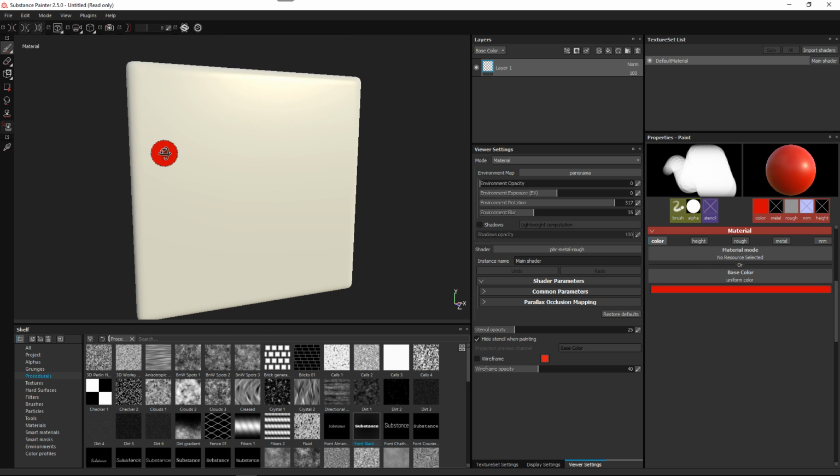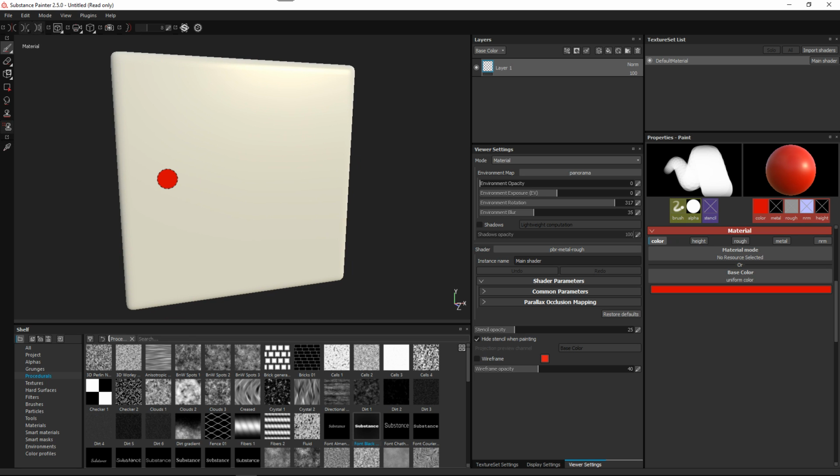All right, so here I'm on this, and this is really where I'm excited about this mirror tool, because there have been so many times when I've needed to do something like this, and we couldn't do it. And there are a lot of people using Substance Painter to create some tiling textures and such. You can do that with a couple of tricks in the way that you set up your UV layout so you can mirror things as you paint a stroke. But because Substance Painter is trying to always paint a continuous stroke across discontinuous UV edges, what you miss out on is the actual mirrored stroke within the 0 to 1 space. So long story short, we can finally do that.